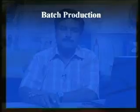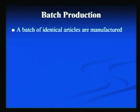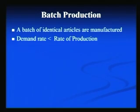Another type of production system is batch production. If you look at the characteristics of batch production, a batch of identical articles are manufactured in such an environment. For example, say printing of a textbook, we manufacture 100 copies of the textbook. That means the article is the same, only thing is that it is manufactured in limited quantities. Another characteristic of this system is that the demand rate is usually less than the rate of production. So, basically when we produce a batch of identical articles, that means we have to keep that batch in our store for some time. So, there will be a build up of inventory of the finished products in this type of situation.